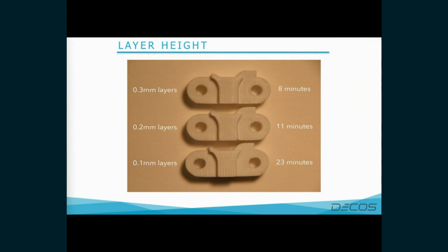When deciding on a layer height, it is also important to consider whether the part will be post processed. A higher layer height may be a better choice if the print is going to be sanded, acetone smoothened, or painted.